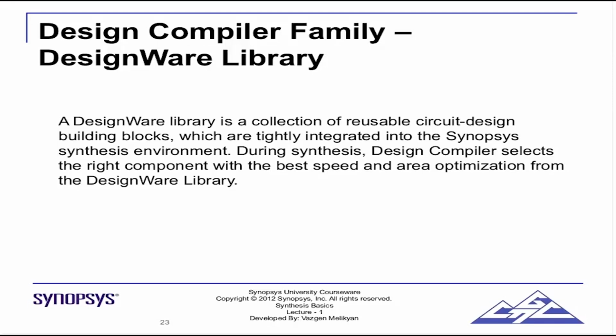So, let's say you have the license for this feature available, and let's say you write A + B in your RTL code. Assume A and B to be 8-bit. Now, what we are doing here is an 8-bit addition. That adder will not be a simple adder. This DesignWare library contains a lot of adders: ripple adder, carry look-ahead, carry save, and so on. It implements all the adder architectures, and you could use them or tell the tool by simply writing A + B.